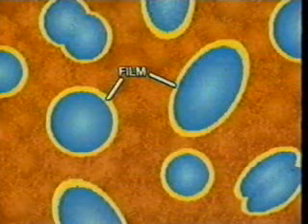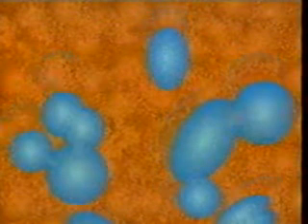An emulsifying agent promotes the formation and stability of an emulsion. The agent collects on the surface of water droplets, forming a tough film which prevents the droplets from joining together to create larger droplets. Asphalt, resins, paraffins, and oil-soluble organic acids are emulsifying agents commonly found in oil field emulsions. Each oil field will have its own individual compound of emulsifying agents. In order to break an emulsion, the film must be neutralized or destroyed through treatment.